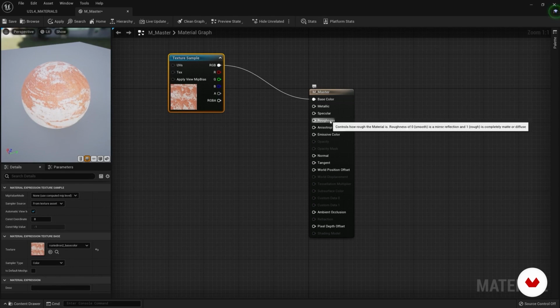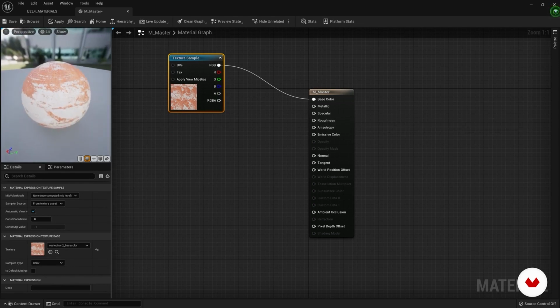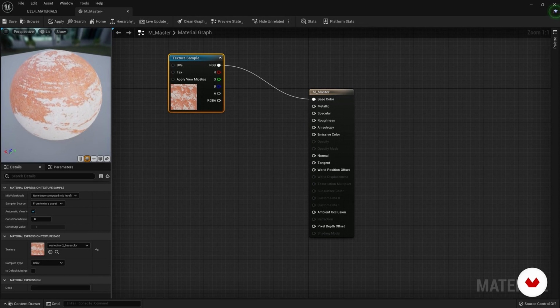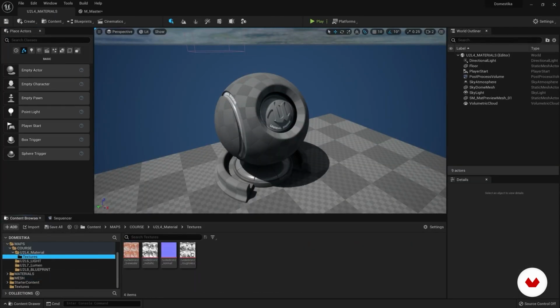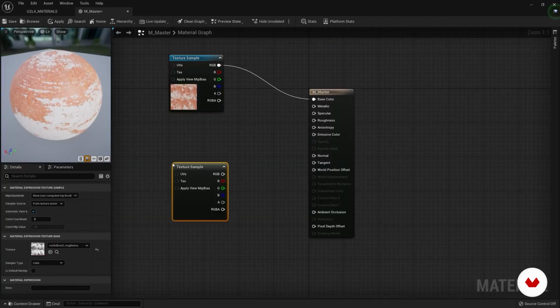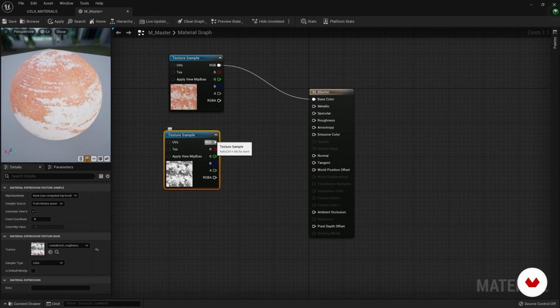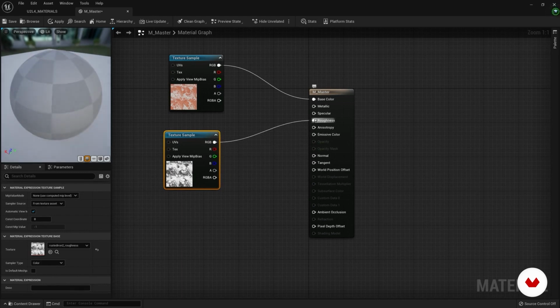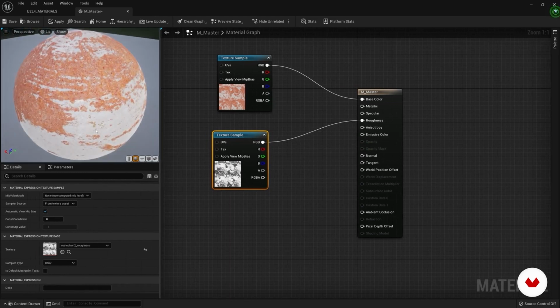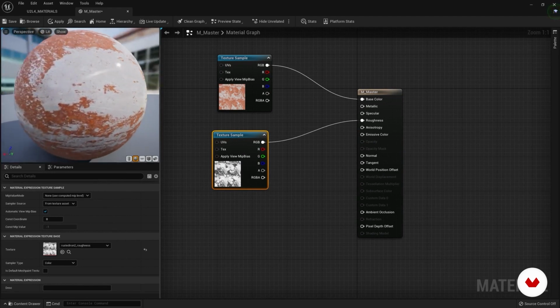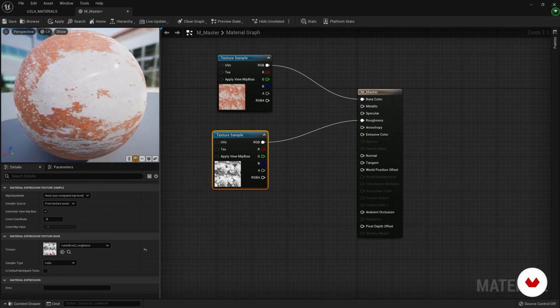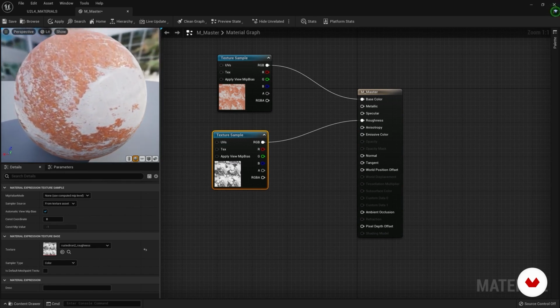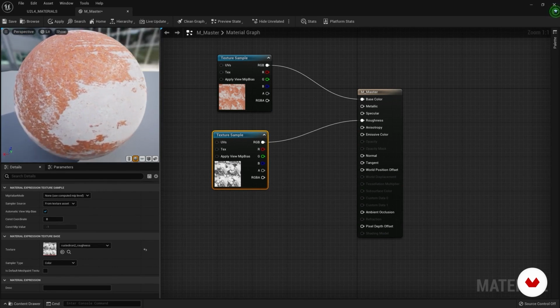Now let's go to define the roughness, that is, where this material is most reflective. Let's insert the roughness map. We drag it into the material editor. Let's drag it into roughness. If we now go and see the clearest and most reflective part, the rusty part does not reflect.